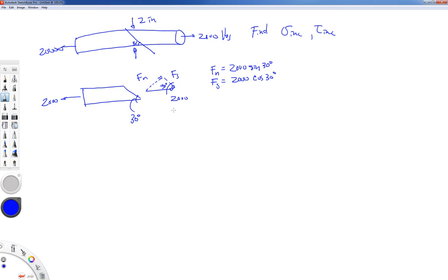Now to find the area of the inclined plane, this may look a little bit different because it's a circular cross-section, but we still need the slant length. I'll identify that as L in this picture, and what we know is the diameter. If I look at that picture, the sine of 30 degrees would be equal to D over L, so that means that the slant length is equal to D, in this case divided by the sine of 30 degrees. If we were to draw this in 3D, let's see if I can do that. The shape of the cross-section would actually be elliptical.